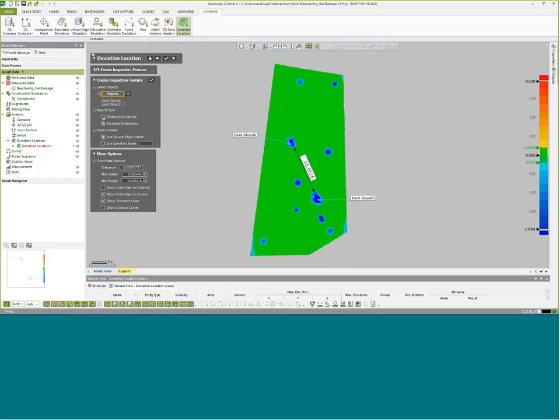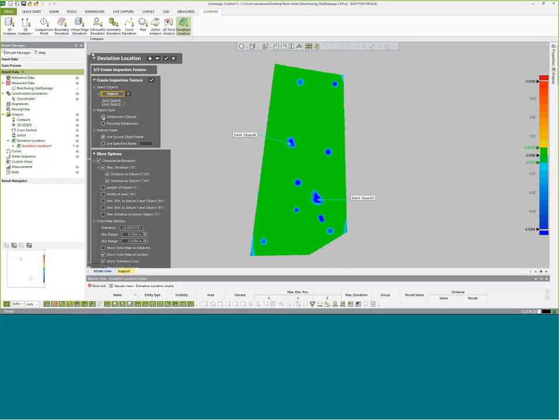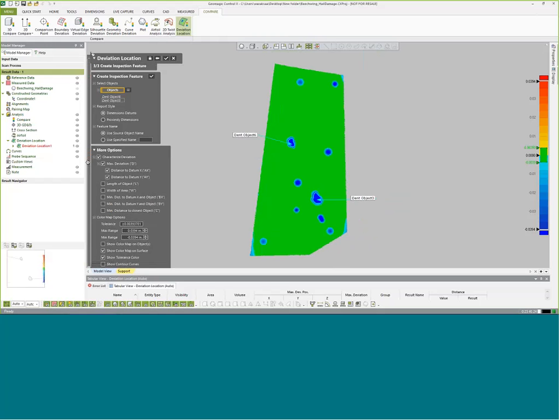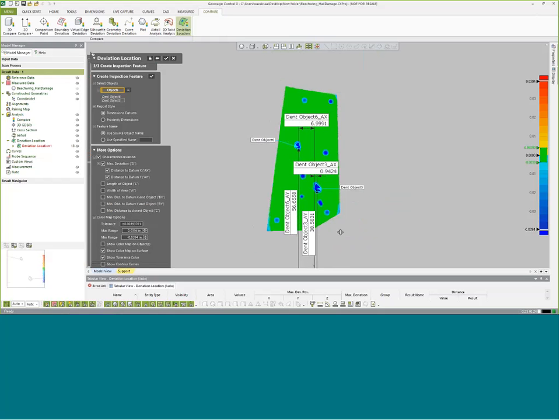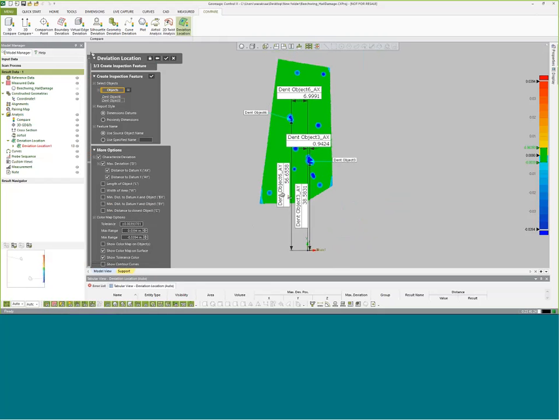And maybe instead of just doing that proximity dimension, maybe we could go into the dimension datum style if we want a little bit more information. So let's go into dimension datum style here. A couple different things we can do. So this max deviation and distance to datum. These measurements will relate back to where our coordinate system was based. So you can see that they're measuring from back where our coordinate system was, so we can classify the distance of where those objects are based on that, and it's measuring essentially at the deepest point, like center of mass of where that deviation is.